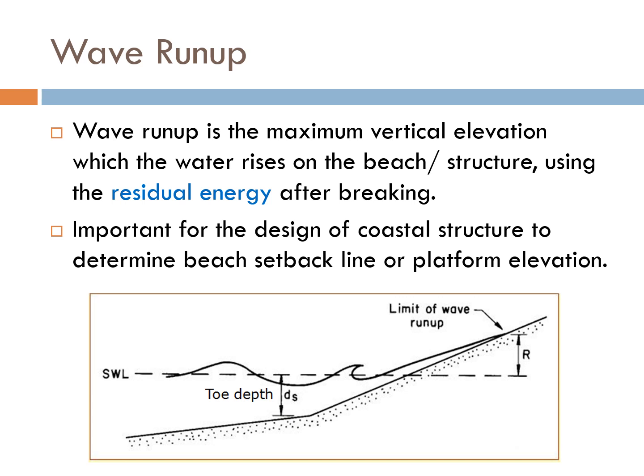So for example, over here, we have the still water line, and the wave is actually able to run up the shore up to this point. So that will be the total run-up measured from the still water line. If this is a structure with a sloped surface, then the same approach to solve the problem is also applicable.